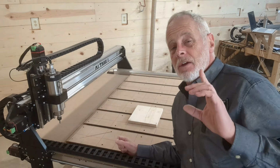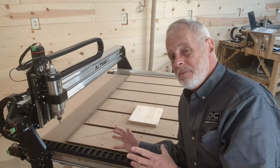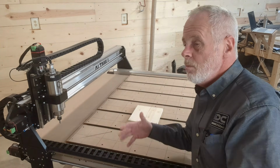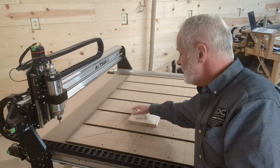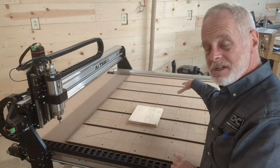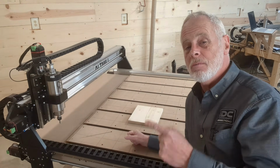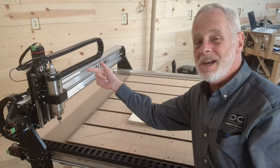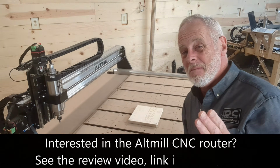In fact, there's one better on this one: you can design your project piece on a template based on the grid, where you open your project design and it has the grid in it already. And you just design your project somewhere on that grid. And then you place the project piece on the appropriate grid on your machine, send the machine home, zero it out, and start your program from there. In other words, you don't probe X and Y, because your X and Y 0 points are the machine home. That's your project origin. That's actually a better way of doing it.